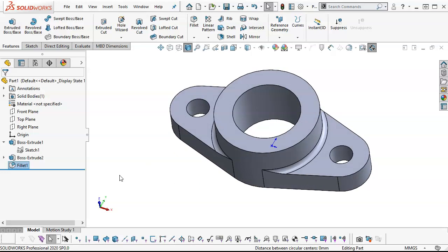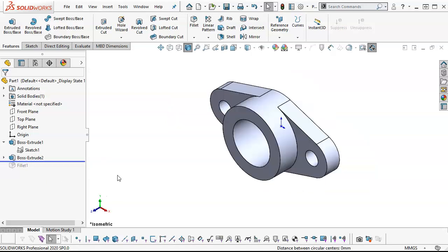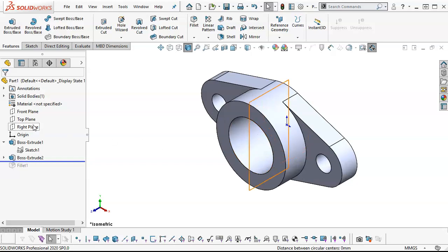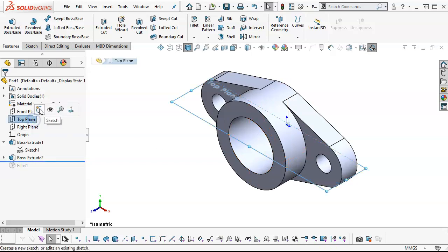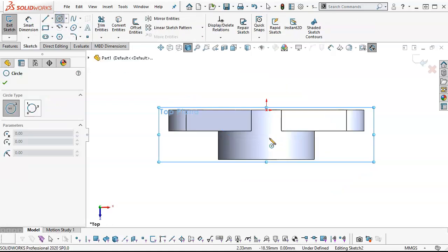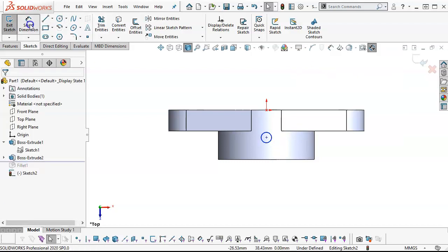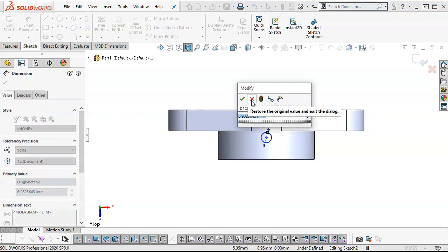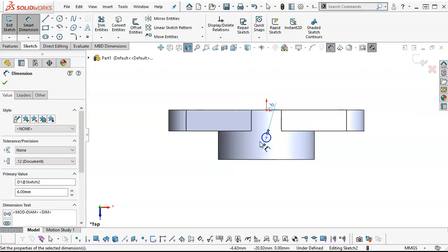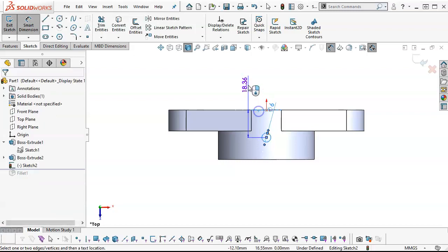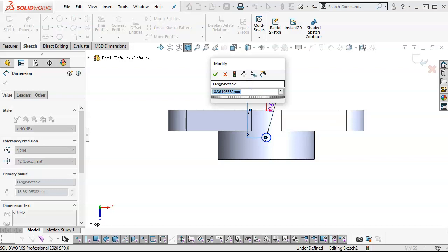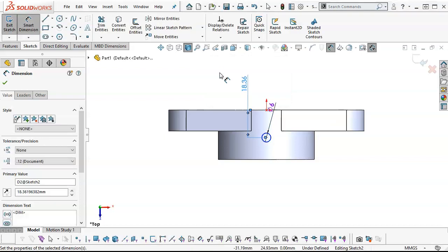So the one that I missed is the 6mm hole, and so if I go to Control 7, it sort of looks like they're dimetric right now. My choices are, and probably the easiest one will be to select the top plane. And I'm going to look for that inference line that it's vertical to the origin. And we have a distance from, well, okay, that's the diameter, since I missed the edge of the part. And we have a depth, it was from the top, so let's go ahead and accept it.